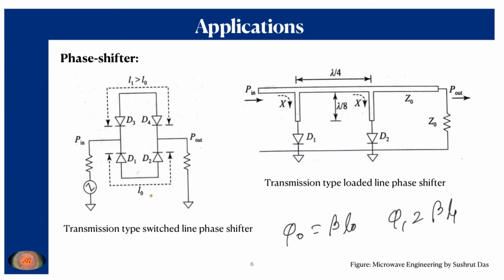Therefore, for a low frequency signal in the case of forward and reverse bias diodes, even if you consider them ordinary diodes, although they are not, when you apply this mechanism you will not experience this phase shifting operation, because in the case of low frequency the wavelength is much larger than the dimension of the circuit. So that phase shifting operation is not possible to be observed.